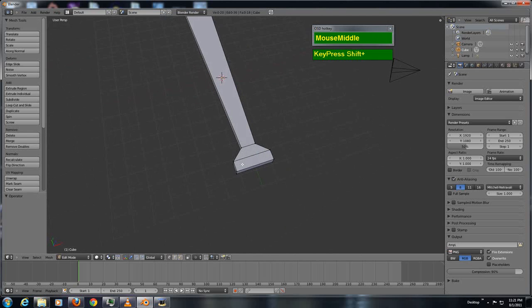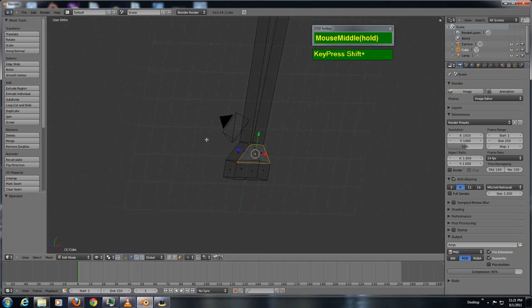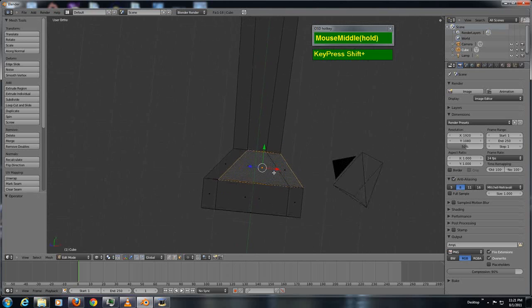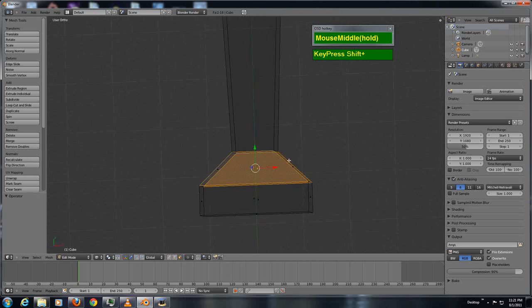Okay, so to do that, let me switch back to the wireframe view again by pressing Z. Then I'm going to go to the top view, and right now I'm in top perspective view. I'm going to press 5 to toggle into the orthographic view. I'm going to press Control Tab, and go back to the face selection mode, and select the top face. I'm just temporarily going to middle mouse click and drag, and you can see the bottom face is selected. I want these 2 faces to be selected. Holding down Shift, right mouse click and select. So now I've got the 2 faces selected.